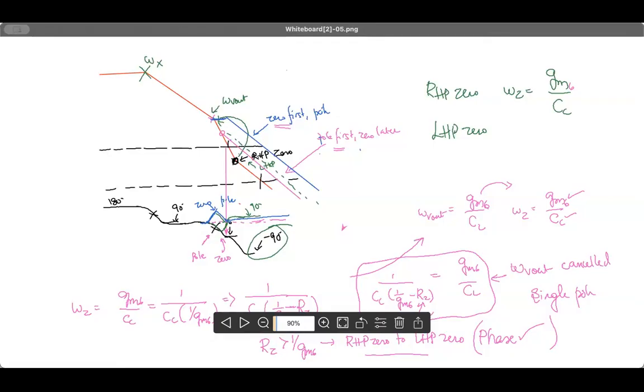Although the slope becomes better, you see the slope is just added by plus 20 dB per decade slope. You added the slope, however, the phase has gone bad. So the overall shift in the phase is 180 to 90. The second pole contributes another 90. The zero contributes another 90.